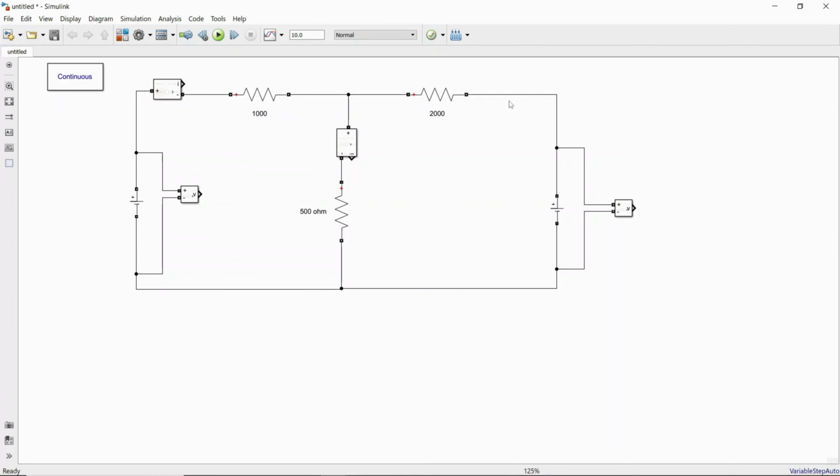The source is from this side, and current flows in this direction. This should be a positive terminal. Therefore, remove this connection and use this ammeter. Just copy it, Control C, Control V, and you see here it has to rotate. Use Control R, it will rotate. So this is the direction. The entering direction will be positive, just connect to positive, and the leaving direction is negative, just connect to negative. Just move it up if you want to make it more beautiful.